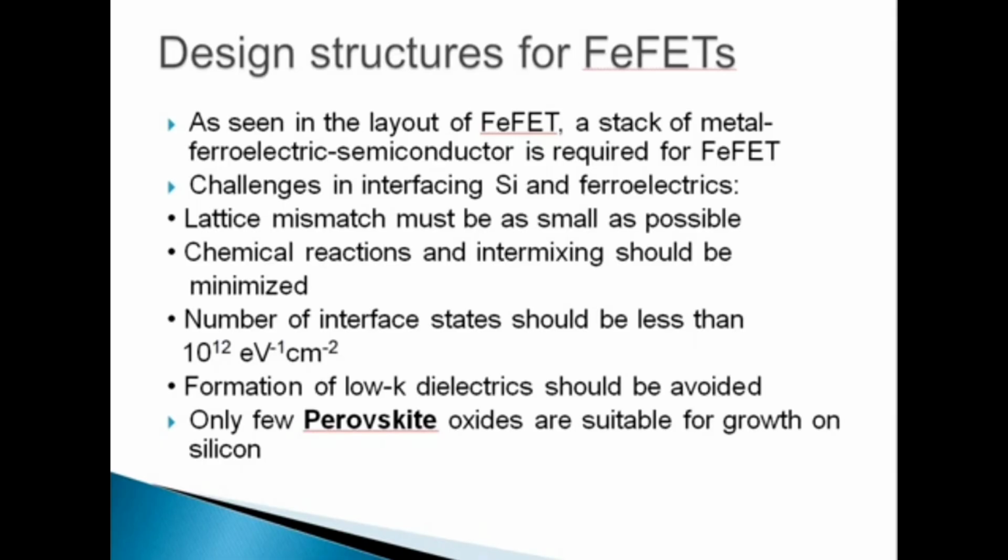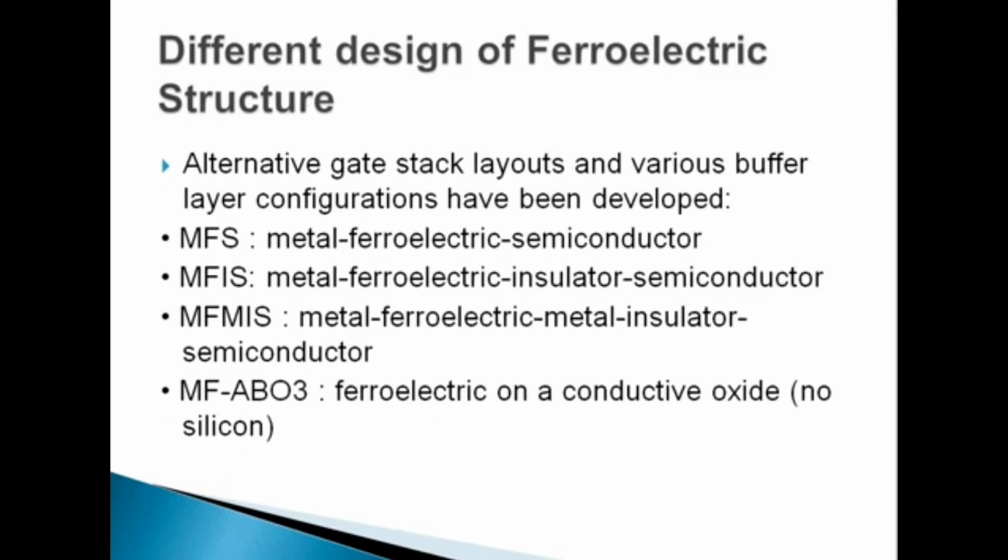Fourth, formation of a low-K dielectric should be avoided. Only a few perovskite oxides are suitable for growth on silicon material. Different designs of ferroelectric structure: alternative gate stack layouts and various buffer layer configurations have been developed.